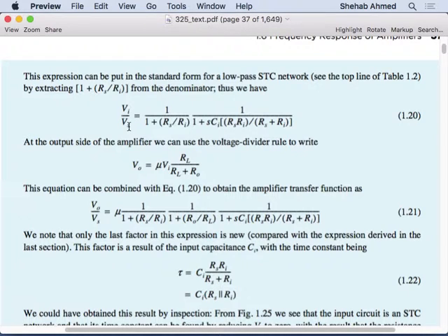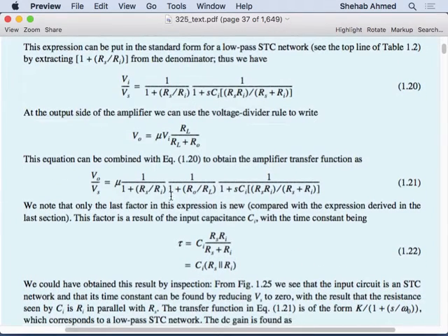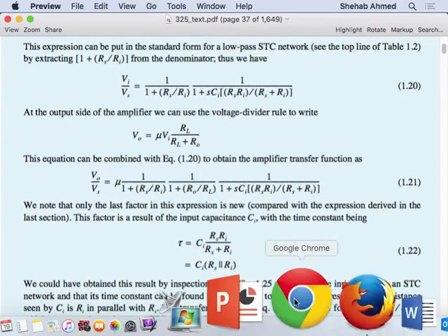V output and sensor input: now we're going to start playing with the sensor input. I will put different data at the sensor input and see what we get at the output. This is the relationship that will relate those. I substituted for VI here and found the relationship between V output and VS, and algebraically I manipulated it such that I have a constant K. All of this is now constant K.